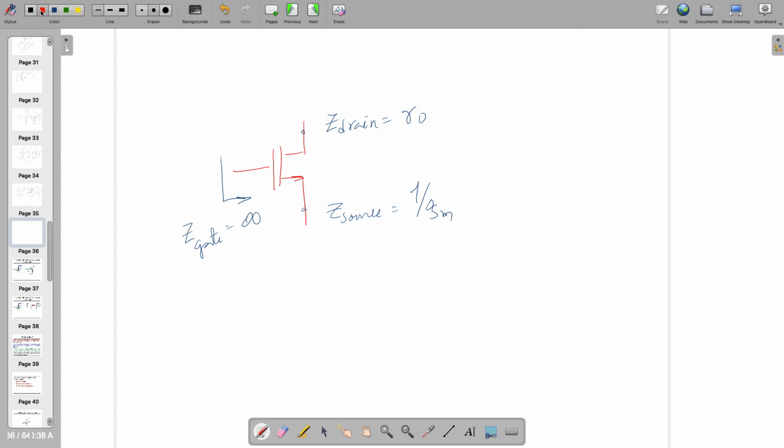You have to look at the path of source and in the drain, and you have to take the ratio of that, which is going to give you the gain, right? So for this case, it's minus GM times RO. Minus sign denotes that the current is flowing in an opposite direction while doing the Thevenin analysis. So we kept minus over here, right? And the drain current and source currents are same.